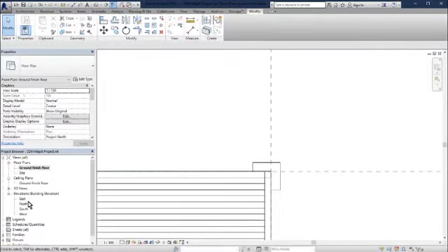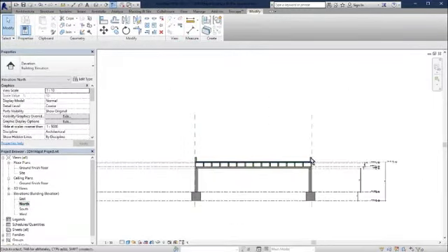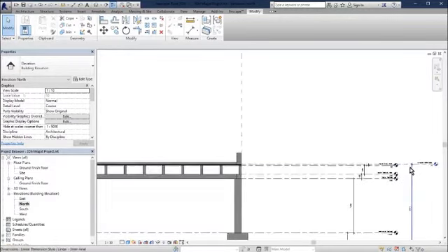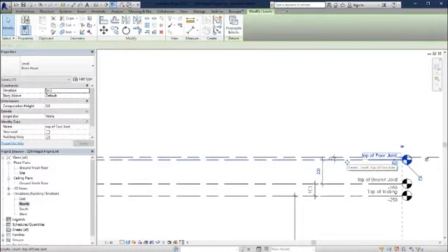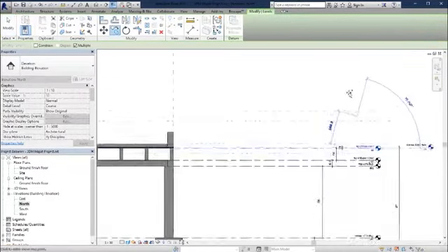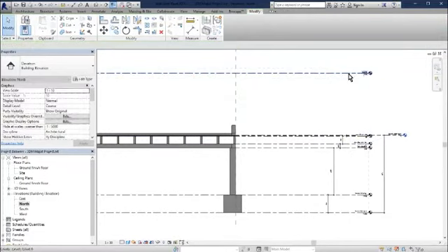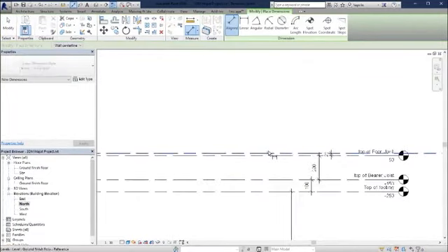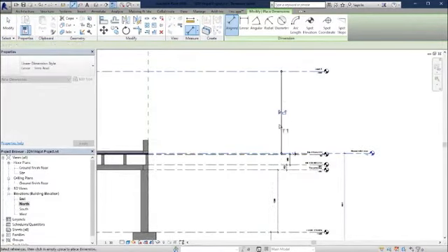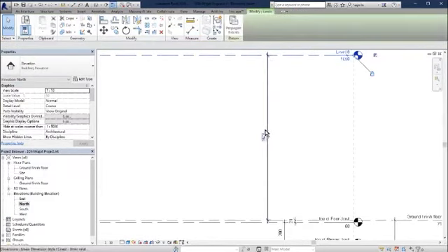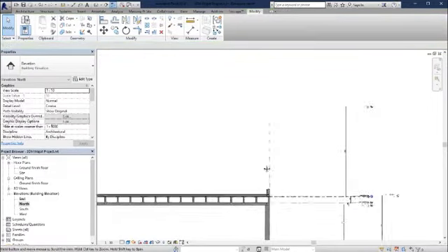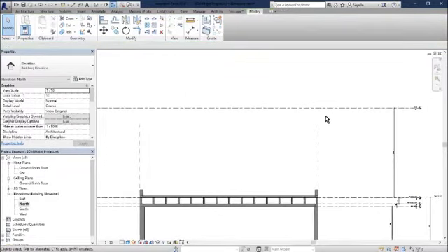Let's choose OK for now. And if we look back on our view here, we need to set how tall our floor level is going to be. So mine is going to be 10 feet. So I'm going to copy a level up, and this level here, it's another empty level. I'm going to use my dimension lines and go from the ground floor to here. And I'm going to make this 10 feet, about 3,000 millimeters. So that is going to be pretty much the height.